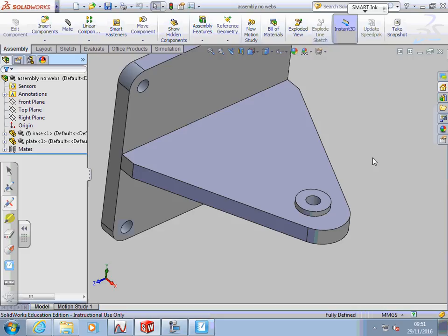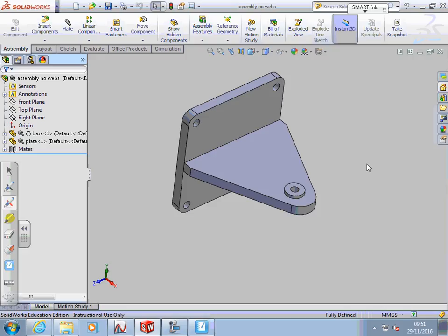Right, people, just a couple of navigation things with regard to SolidWorks. Are you all listening? If you double click the wheel, you fit the model to the screen. So if you've zoomed in or zoomed right out, a double click on the wheel will get you back to there.